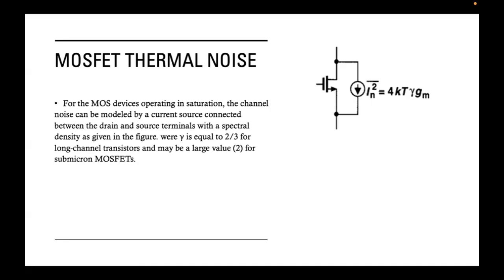If we are considering an N-channel MOSFET, we can consider it as a resistive path, where the resistance is mainly related to the channel condition after the pinch-off point. So herein, we are using a model typical of what we did with our resistance.